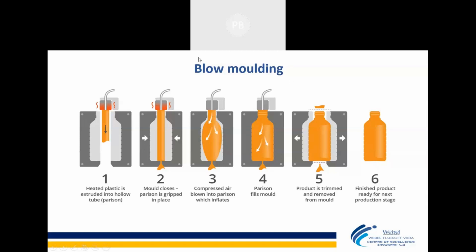In injection molding, the material is in a raw molten stage, but here there will be no molten stage. So here you can directly use dies made by 3D printing. And there are a lot of 3D printing materials which can withstand a certain level of temperature, around 100, 200, even 300 degrees. So blow molding is one of the processes where we make bottle kind of things, and you can directly make the mold with a 3D printer. So 3D printing is also helping the blow molding industry.